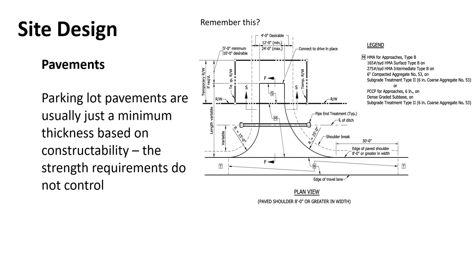And what we look at there is that maximum aggregate size. We want the total pavement depth to be 2 or 3 times that maximum aggregate size, so we can pack it all in there nicely and have a good mix of a range of sizes, and we don't have lumpy asphalt with rock sticking out of it. That's not good, right? And we'd probably want to be more towards the 3 inch, right?